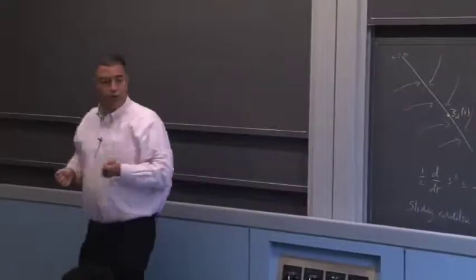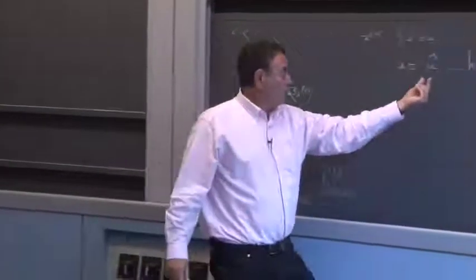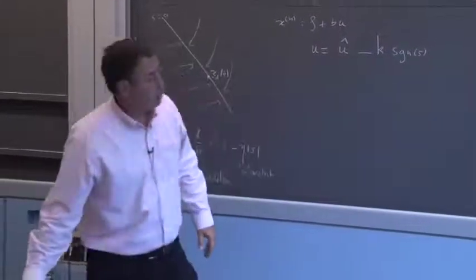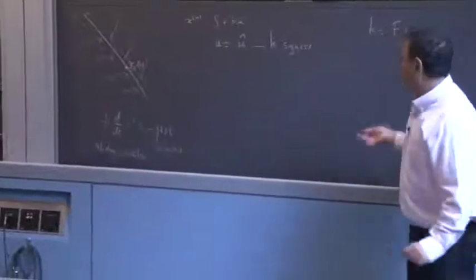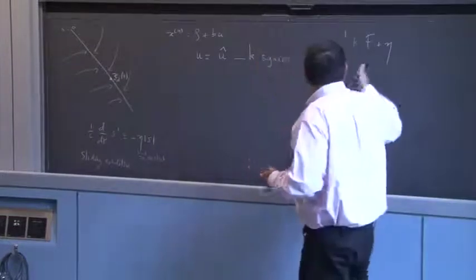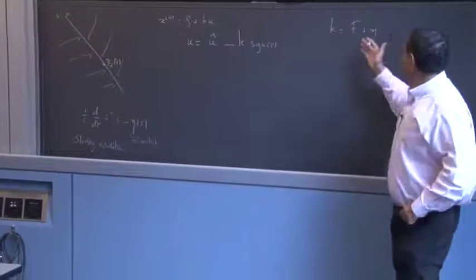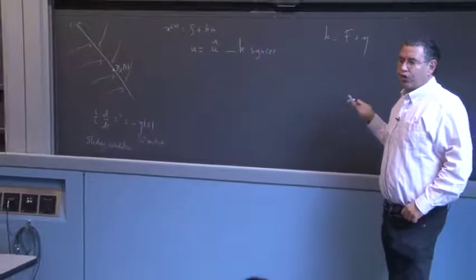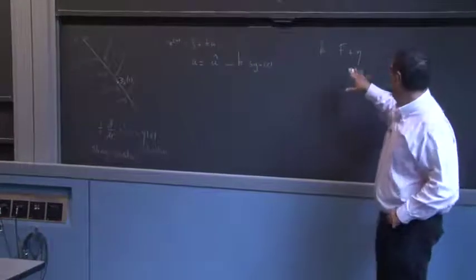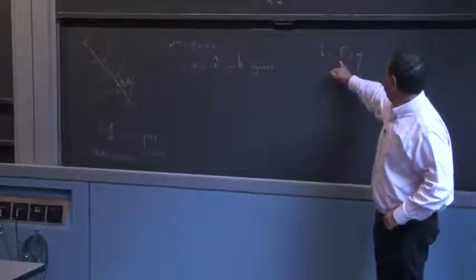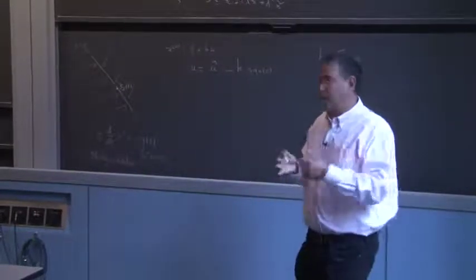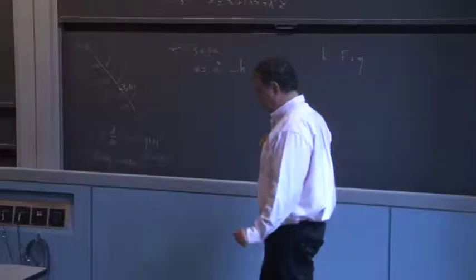The amount of gain we put was basically how much uncertainty we had plus eta. Eta has to do with how long it takes to reach the surface, but from a practical point of view you can almost view it as a small positive constant, the same kind you would use to avoid dividing by 0. What matters is this term, which reflects what you know about the dynamics and the uncertainty about the dynamics. Then you add this small term here.